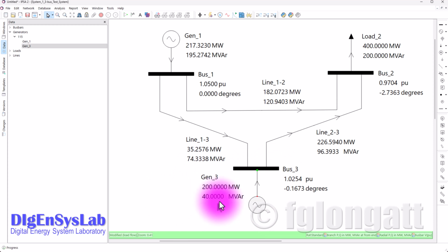What I am trying to tell you is that in order to keep this voltage equal to 1.04, we require more reactive power. As the generator is limited to 40, this generator will keep constant this active power, and the generator changes the operational mode from PV, that means constant voltage, to PQ. And in this case, the voltage can drop.